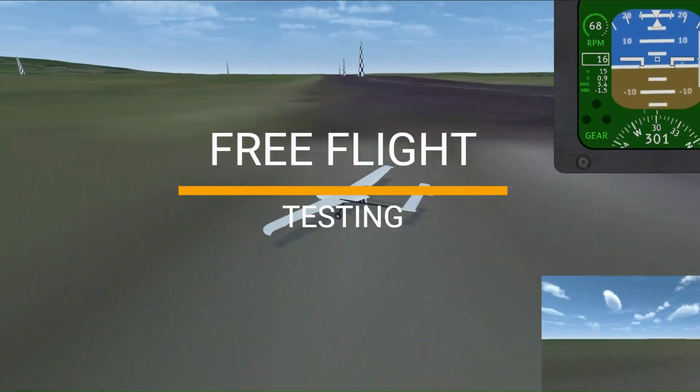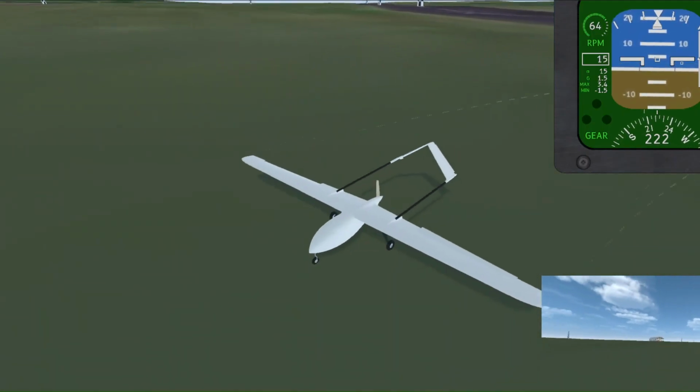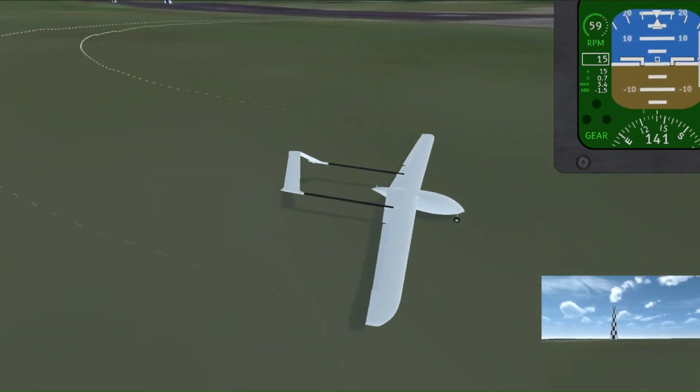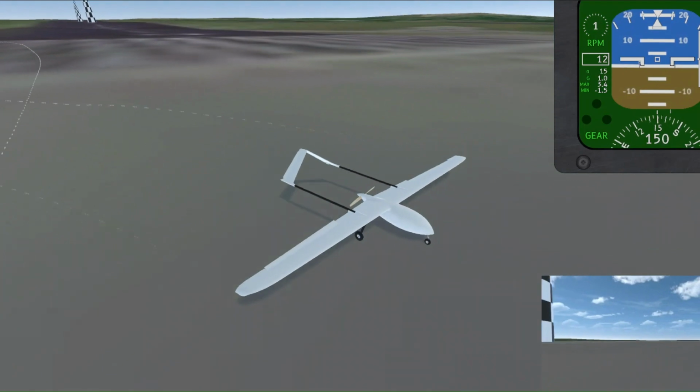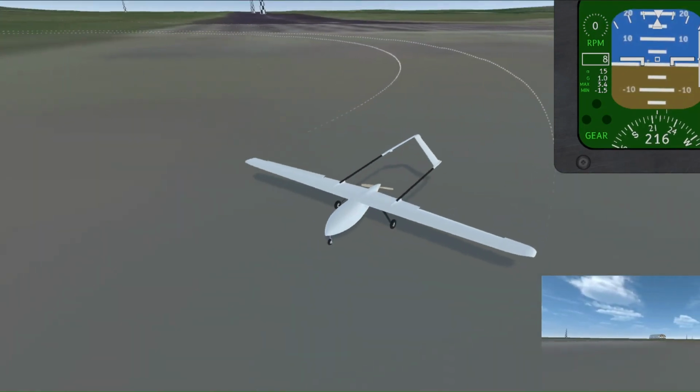The combined nose gear steering and rudder input provides sufficient authority for maneuvering the aircraft on the ground. However, high-speed steering would increase the risk of the wing striking the ground and also put high lateral forces on the nose gear. This could cause nose gear failure.